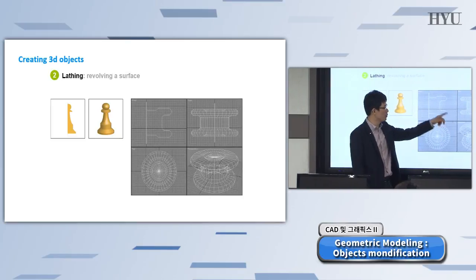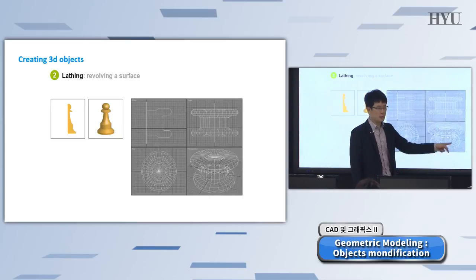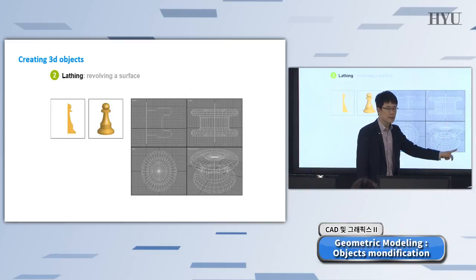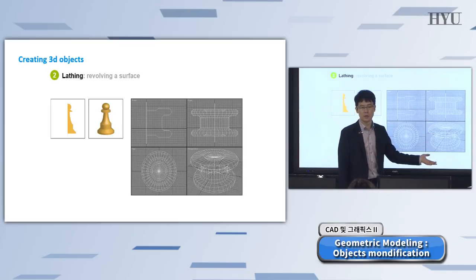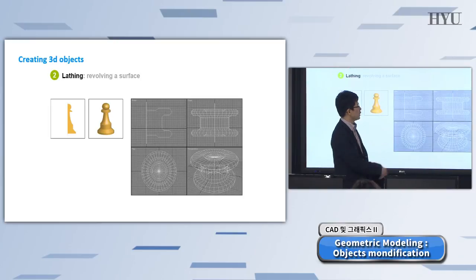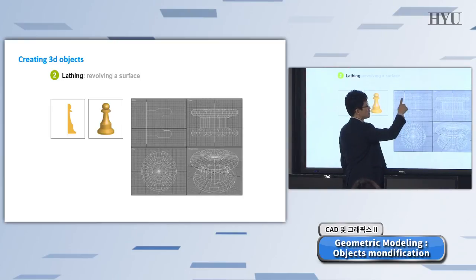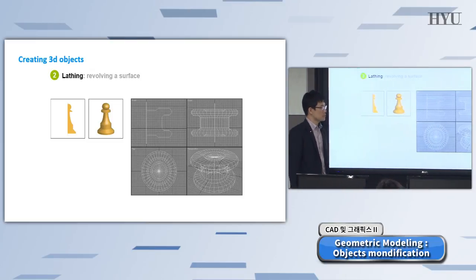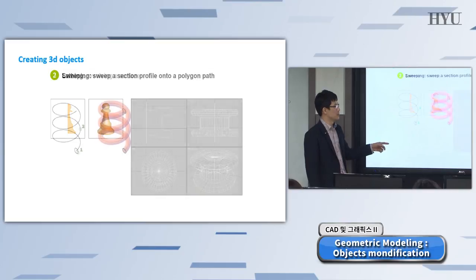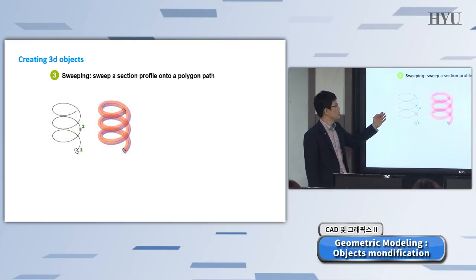Think about this complicated 3D object. It looks complicated. If you create a cylinder primitive and modify it, it's going to be really time consuming. But what if you draw one single axis and a section profile? Simply a rotate modifier will create that geometry for you.